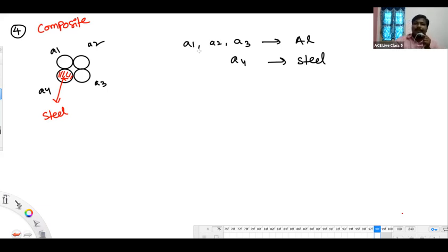Now I am asking one simple question: how to calculate the GMR of this conductor? Just listen to my words. If a number of aluminum strands run in parallel with a steel strand, and you send some current, that current is going to be concentrated mainly in the aluminum wires. The steel wire current can be negligibly small, so the effect of the steel wire can be neglected in the GMR calculation.